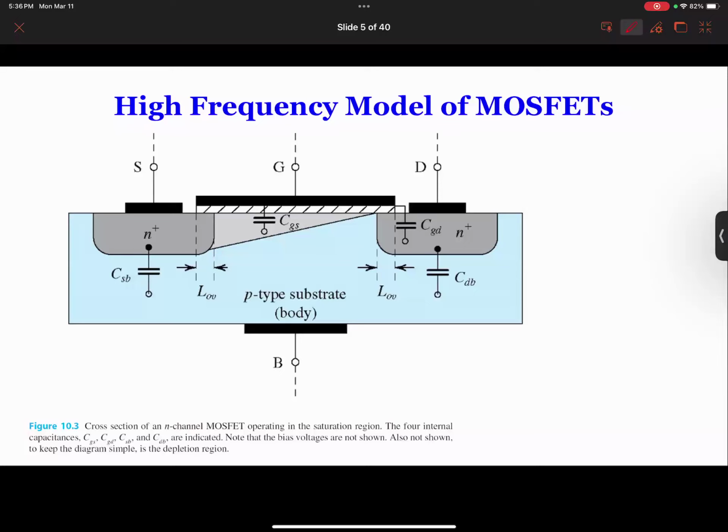When you put a piece of metal, apparently what you're doing is forming a capacitor. Exactly. For low frequency, it doesn't matter because a capacitor looks like an open circuit. But for high frequency, the problem comes in because that little capacitor starts to cause trouble. The reason is that modern MOSFETs operate at megahertz or even tens or hundreds of megahertz. Very little capacitor.